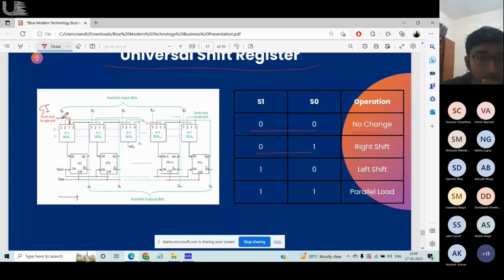So this comes in from the left, gets in here, and becomes the output of this flip flop. Whatever was stored here goes into this one. If you notice, it's connected to this one, right? It comes here, and like that the values get shifted along. And this is my final output which comes out here, the serial output, serial out. This is my output, right?